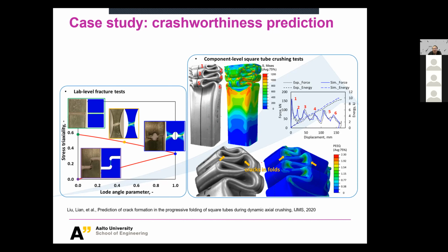And what people worry about when they make this structure in the car is they don't want this kind of component to develop fractures. We just want it to deform in such a way. If you develop a fracture at this point and this component becomes completely two parts, it loses its function, so it cannot protect you from a crash by absorbing energy.